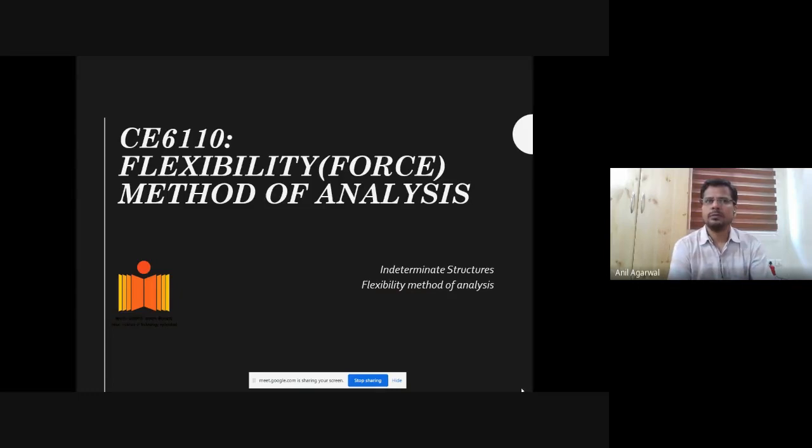Again, for determinate systems, we discussed a few methods to calculate the deflections. As long as you know the internal forces, many of these methods would work. Some of the methods that we had used, one was double integration, then there was one derivative of double integration. What is the name of that method? Anybody? It was like, for beams, it could be used.